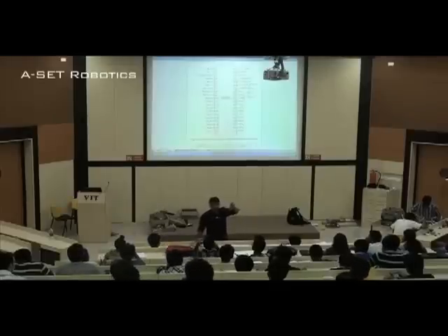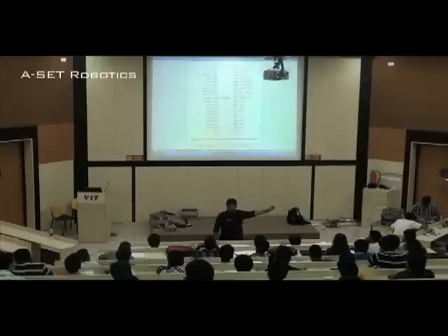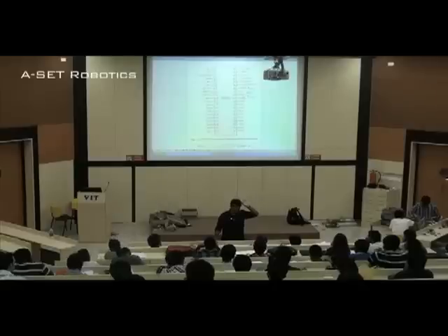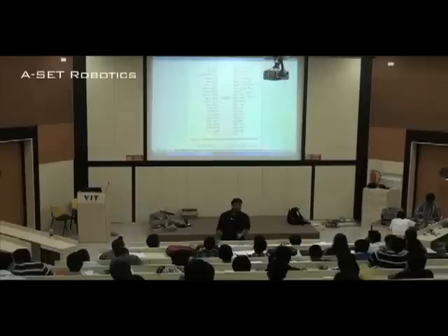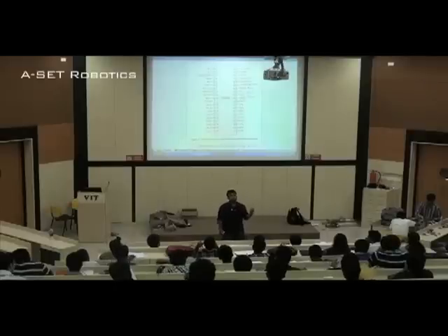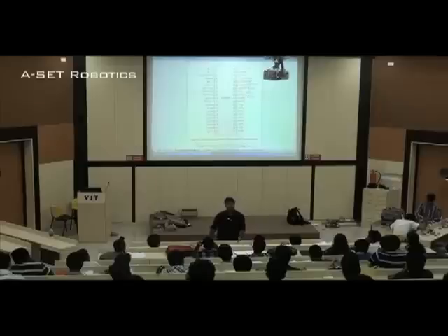And this is the difference between a microprocessor and a microcontroller. All these things would be done by a different device that controls memory and storage. There would be a different controller for that. But in a microcontroller, everything is in the same chip. Memory would be very little. It's possible that it doesn't have any cache memory and directly has the registers.